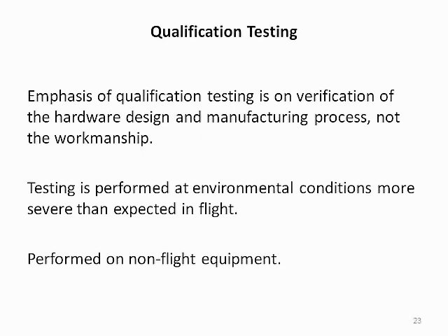In qualification testing, the emphasis is on verification of the hardware design and manufacturing process, not the workmanship. Qualification testing is performed in environmental conditions more severe than expected in flight and is performed on non-flight equipment.